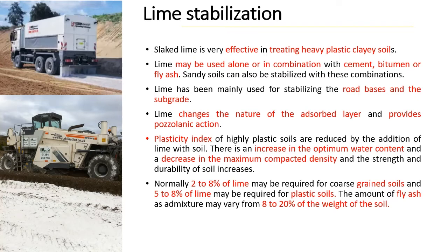The principle involved in lime soil stabilization is the exchange of ions between lime and soil when added. When clay soil is treated with lime, cation exchange takes place between them, which increases the plastic limit and reduces the plasticity index, which finally results in increased stability of the soil. If clay contains gravel in it, then lime acts as a binding material for clayey gravel.